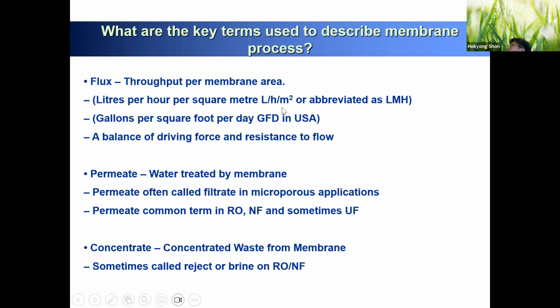So normally when you design your reverse osmosis, we just calculate how much water you need. When you design your seawater desalination plant based on your scenario, you have to design for 250 megaliters per day. So how many membranes do you need? How much water in LMH do you have to produce? And how much pressure do you have to apply to produce your desalinated water? So that's how you have to calculate. Like 1 liter, 1 square meter, 1 hour, you have this much water.